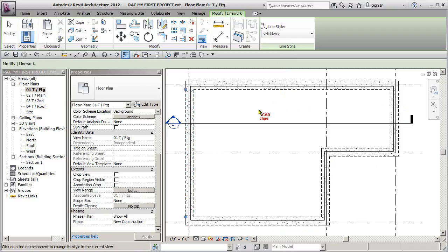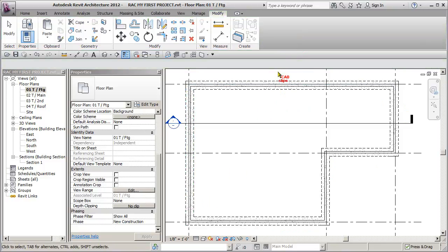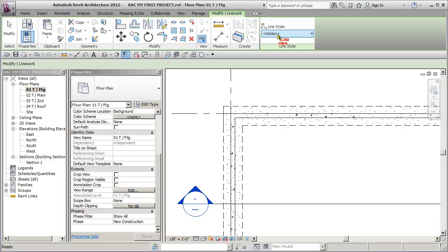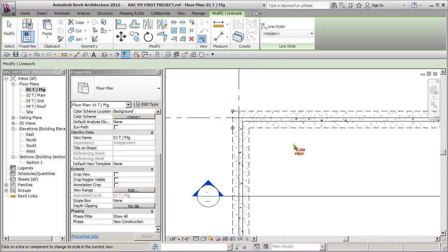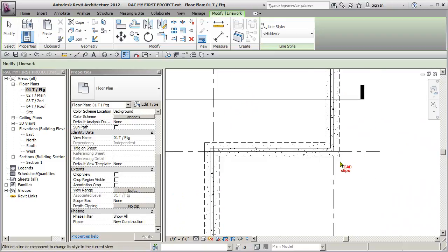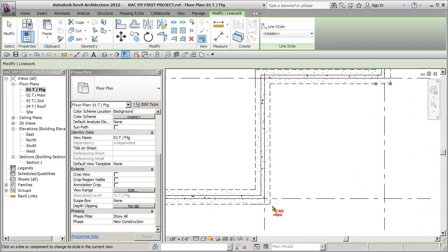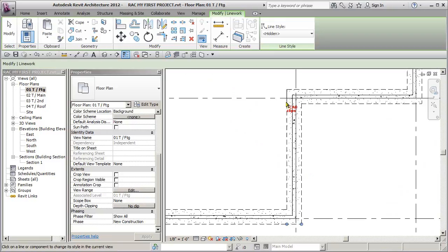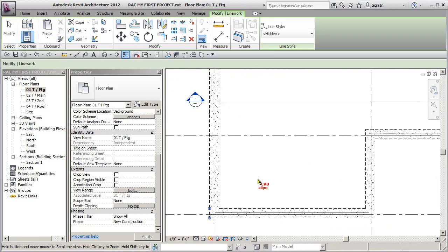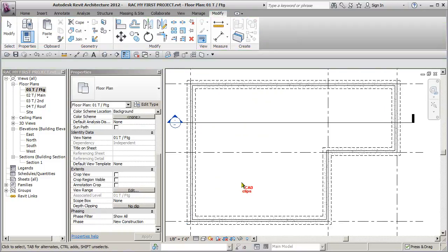Okay, so I can go in and paint those just like that. Escape, escape. So that is taking on the line type hidden. Oops, and I could also do this, right? Hidden. Boom, and then just pick. Do I have to do any more edges? Okay, we can make these so they get mitered at the corners too, so I don't have to go in and do this extra little bit. Okay, so that more or less solves that problem.